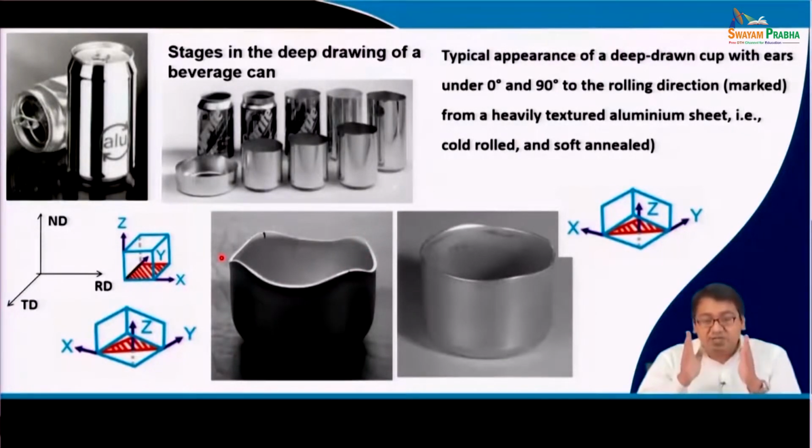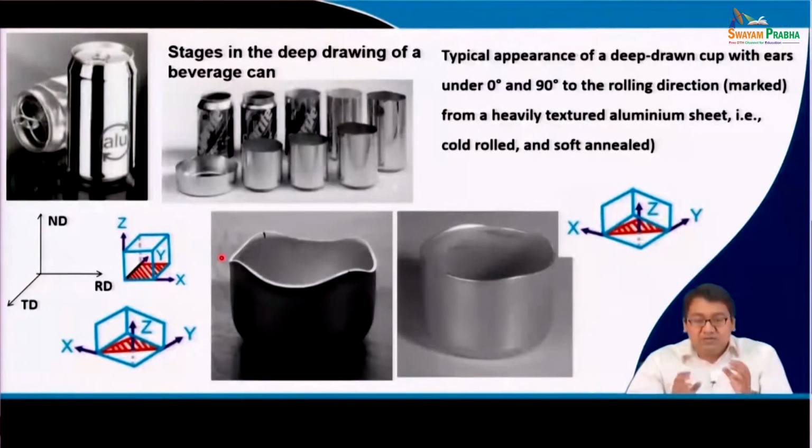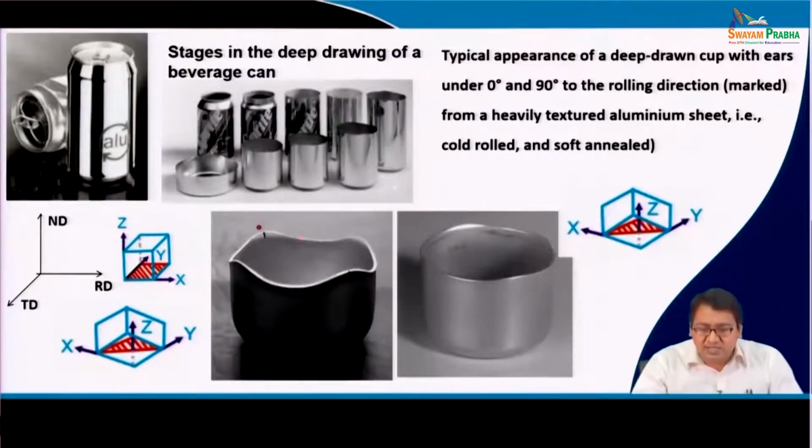But with microstructural engineering, by a simple plastic deformation process which is rolling, to produce a certain texture component very sharp, this particular texture component led to the formation of rolled sheet which could be deep drawn not only to this extent, but with stages of deep drawing to a larger can with a very thin but unnecked cup portion.